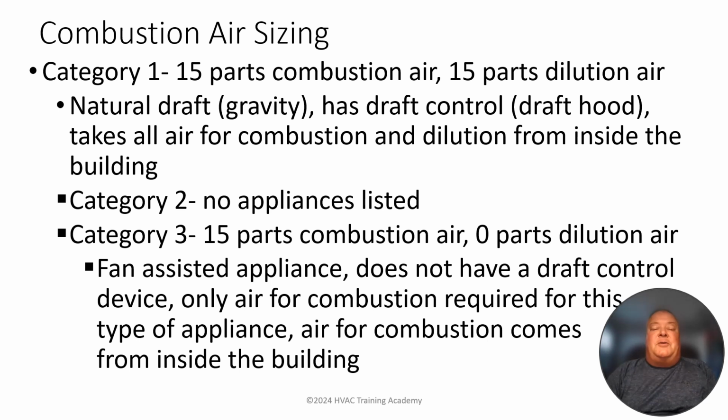Your category 2 appliances, there's no appliances currently listed that utilize category 2. That's basically above 83% efficiency without a fan pushing those flue products through the heat exchanger. Not saying it's impossible to be done, but in today's world, we find it isn't really a necessity. We typically have our higher efficiency pieces with what we call our positive fan pressure types of systems, which are going to be category 3 and 4.